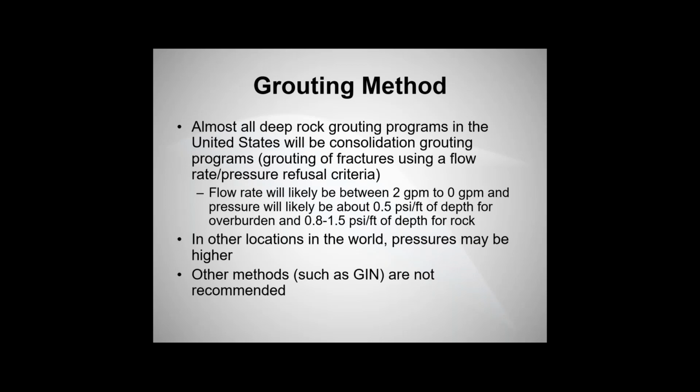Again, the pressure flow criteria, the refusal criteria, is the important aspect of consolidation grouting. There are other methods. One of those is known as the GIN method, and you may hear about that. However, at least in my opinion, it really does not have a place in deep grout curtains for rock.